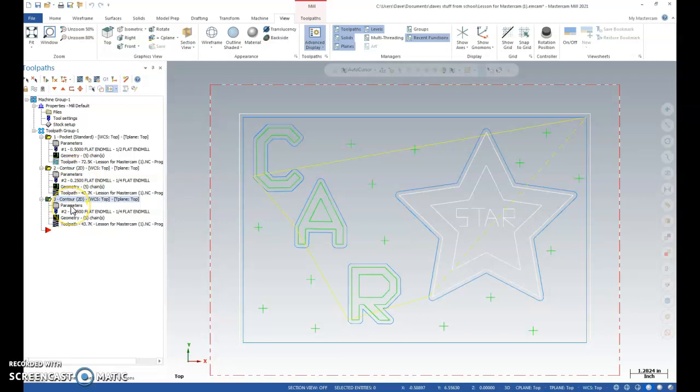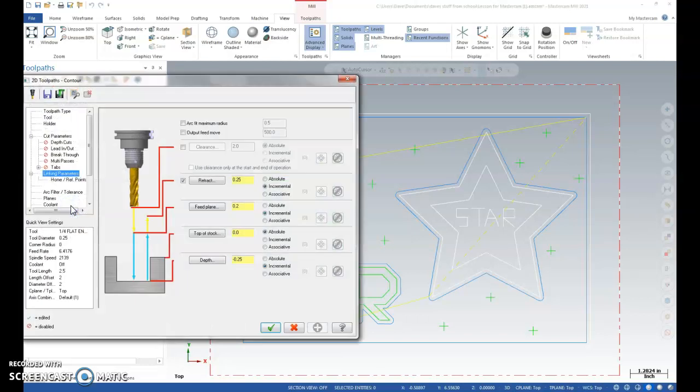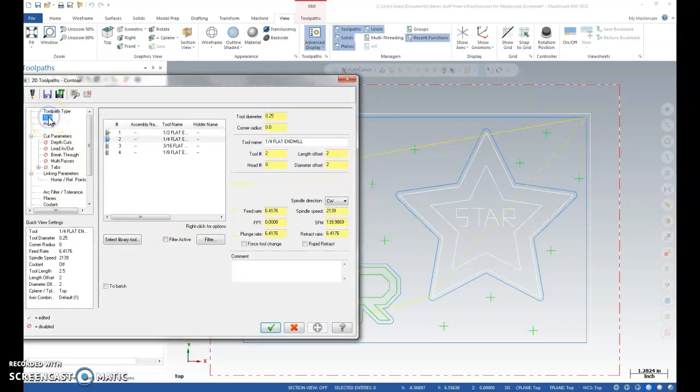Now, it's a repeat of this one, so they are exactly the same, but I can change it. So I just come here to the word parameters. And remember all the things I could change here. One of them was tool. So I go to the tool, and actually I would like to run this guy at 1/8 of an inch. And I did forget to tell you to make sure to put the right speed. So 1/8 of an inch, it's 60, 59, 58, 57. So we'll actually have to fix this one because I should have made the speed 59 here. So this is actually 57. So 57, and that's inches per minute. And this guy is 10, and this guy is 60.